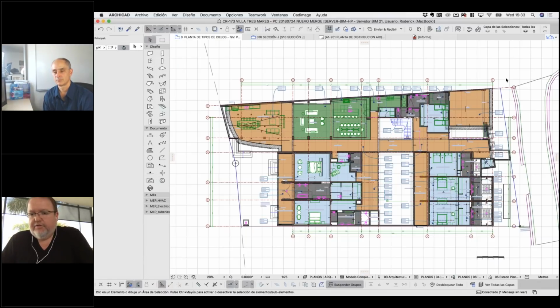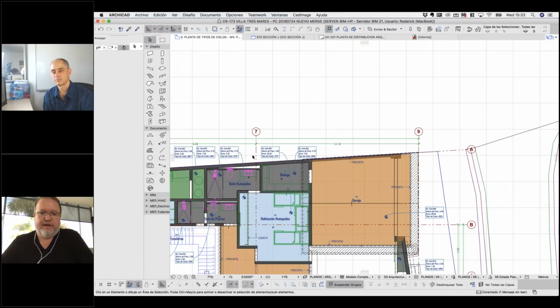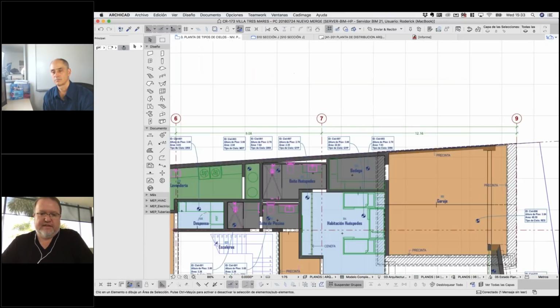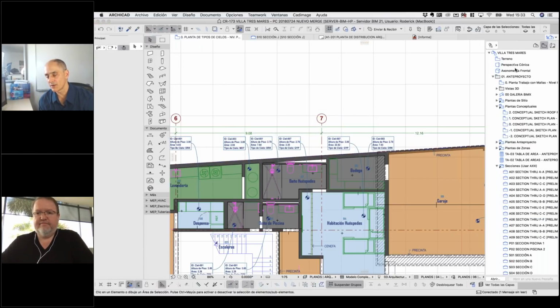And what I have is a graphic override pre-programmed into the template that, based on the composite of the ceiling, represents it in a different color. Therefore, we have a differentiation of what's normal gyprock and what's maybe a wood ceiling, and maybe a cement-based ceiling board. And of course, as part of my favorites, I've got all of these auto text labels completely preset that we just apply via favorite. So let's just focus in on that for a moment.